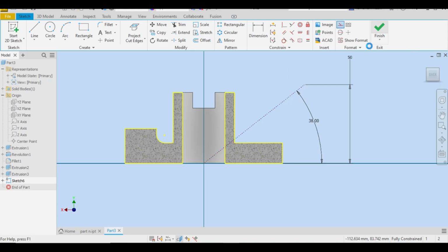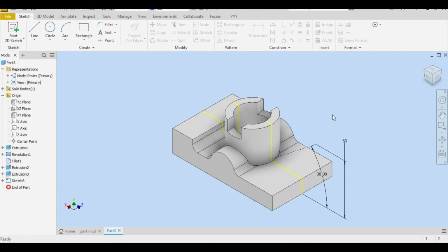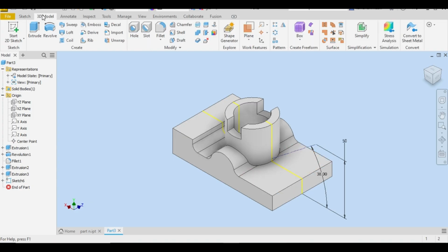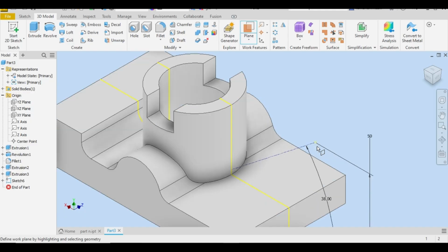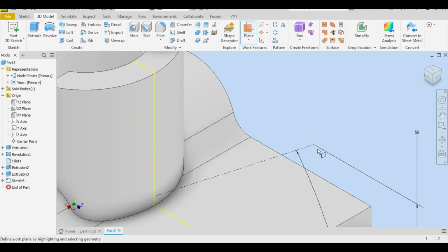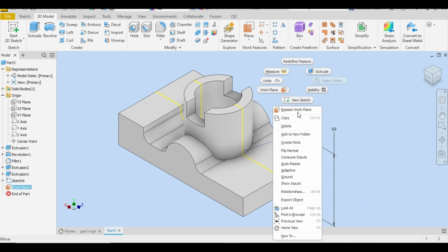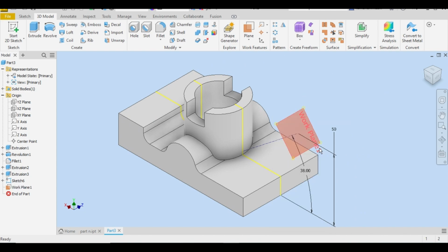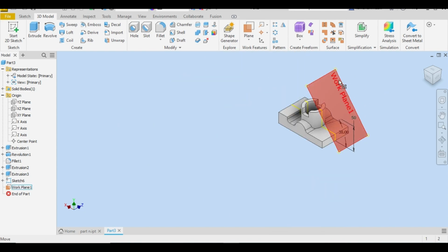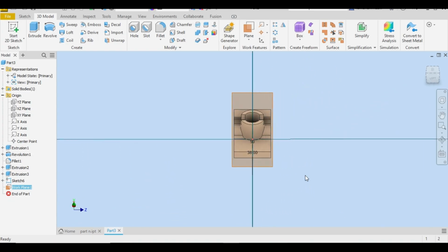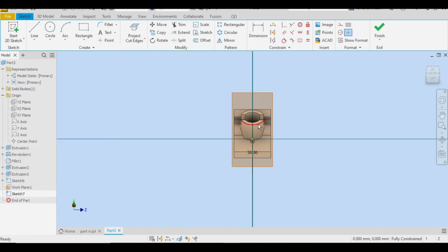Okay, now it's simple. If we want to create a plane here, normal to the point, just select a plane, normal to the point. This is the point. Okay, the plane is perpendicular to the line. Auto resize. Okay, the plane is large now. Let me create sketch at the plane. Let me use project geometry and select this point so we can stick our sketch.